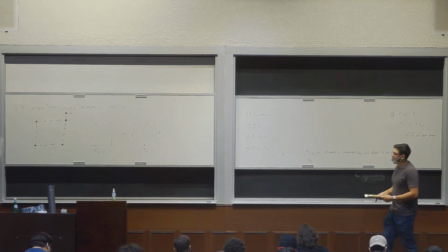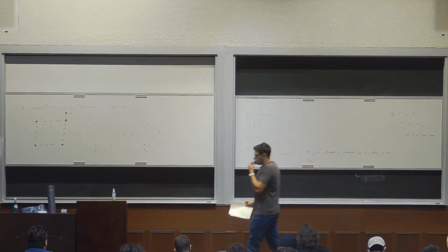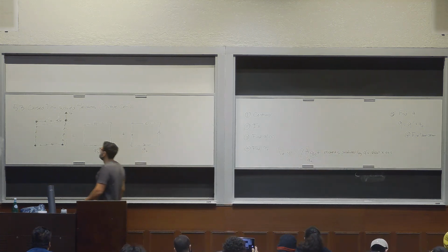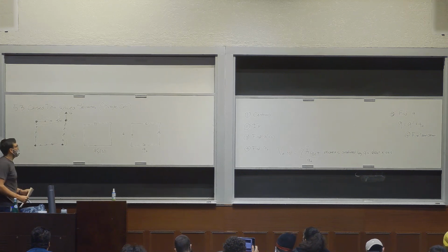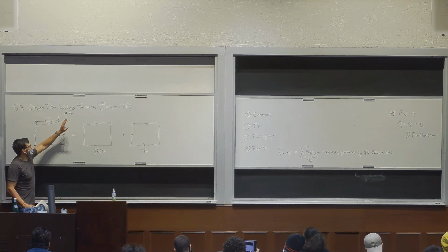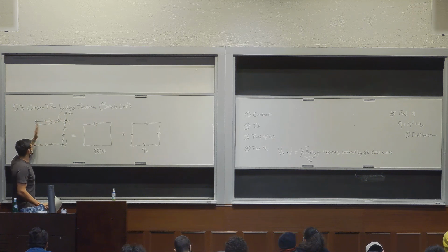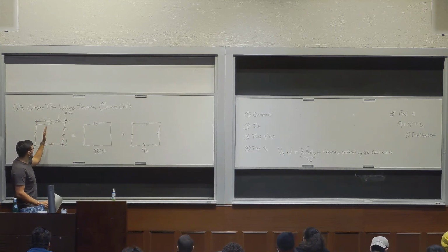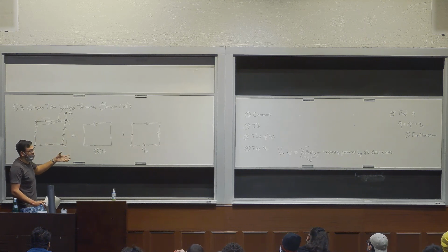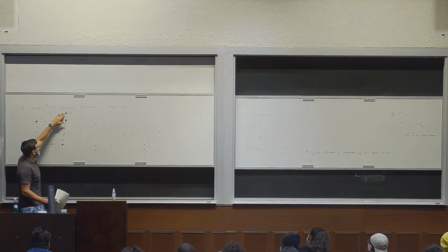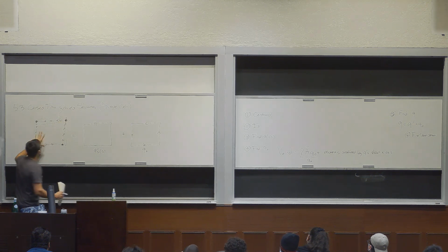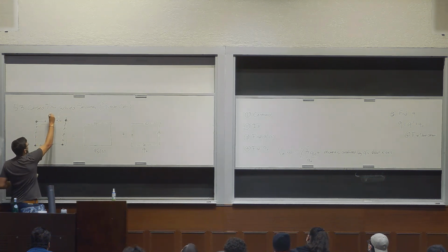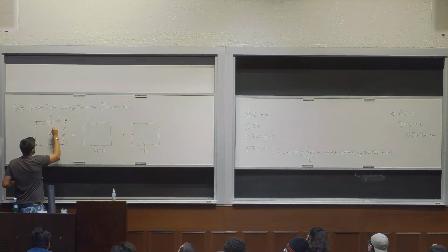So what is the shear center? The shear center is a position about which this Vz, which could be acting anywhere, could vary along any position y. There's a specific position y in which it will produce no torsional deformation. Like in this case, it's a perfectly symmetric system. If Vz was applied right down the middle, that would be the case.